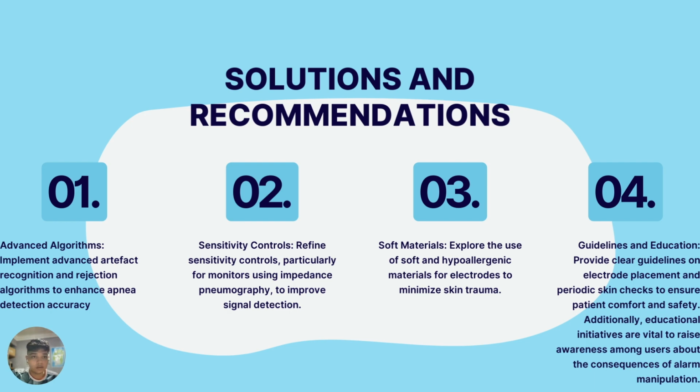Addressing the artifact detection issues requires the implementation of advanced algorithms for artifact recognition and rejection. These algorithms can enhance the accuracy of apnea detection by distinguishing between genuine respiratory signals and artifacts. Manufacturers should prioritize refining sensitivity controls, particularly for monitors utilizing impedance pneumography.